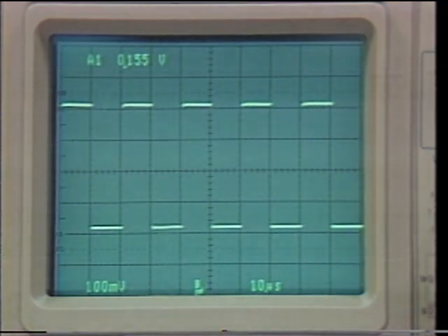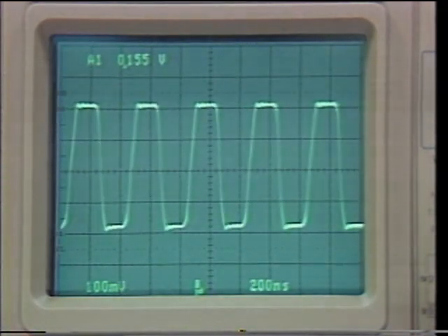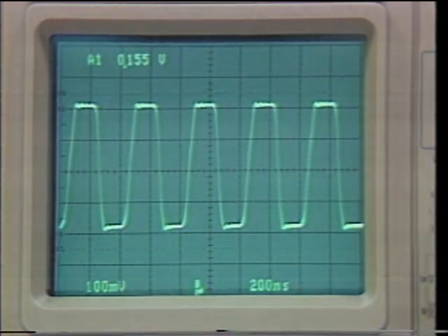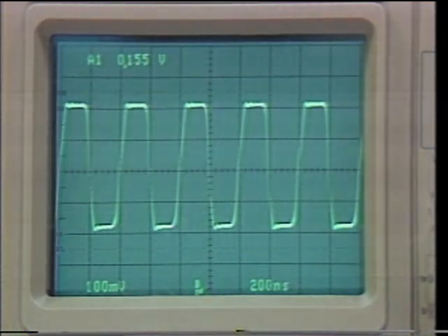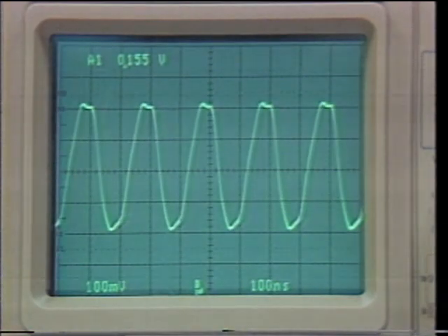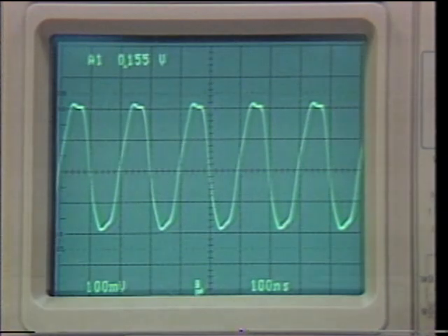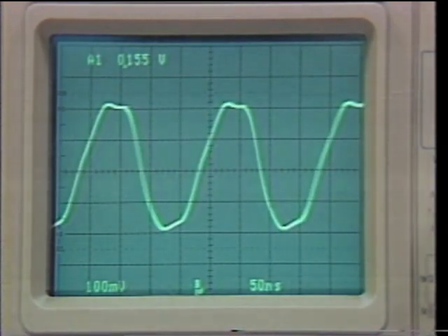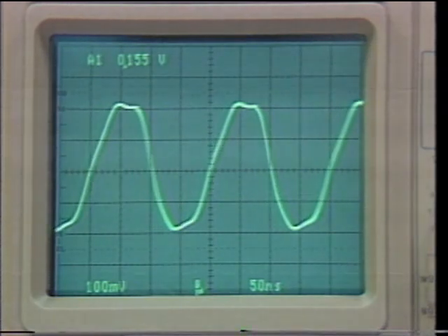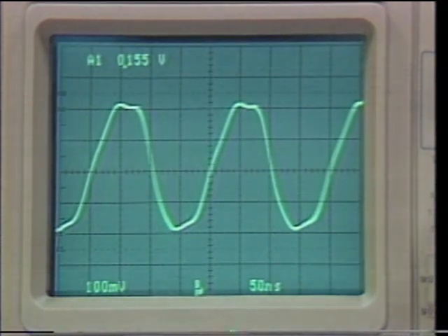Now, as we continue to the very fastest speeds, we begin to see the rise time of the calibrator, and because of the vertical delay, we'll need to reposition the waveform. In fact, we're now at the point where we are at the highest frequency available from the calibrator. So as we continue to higher speeds, we have to use the waveform in a little bit different manner.